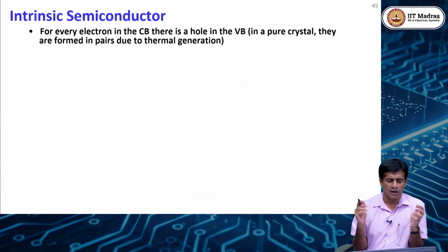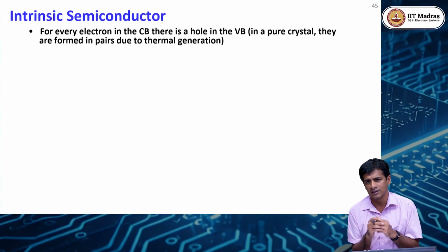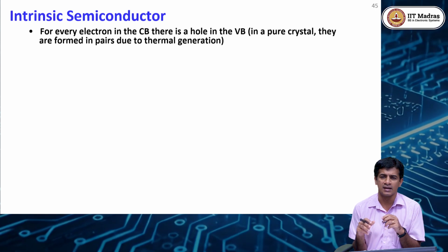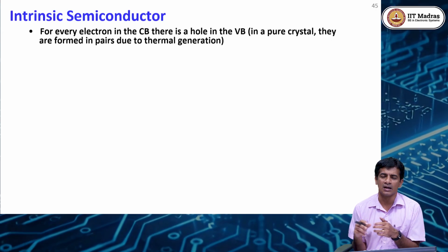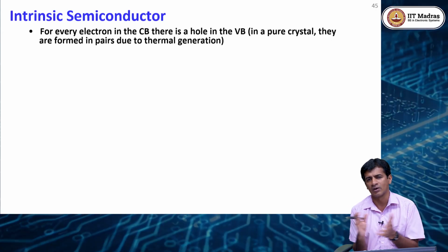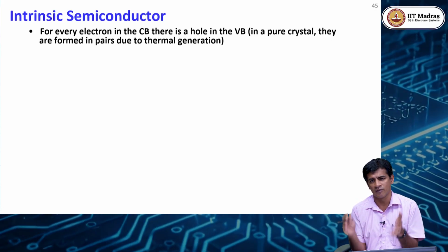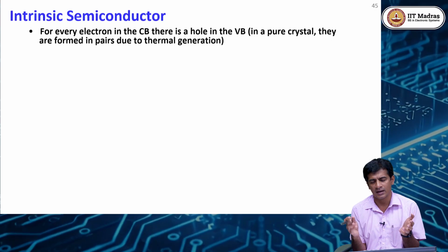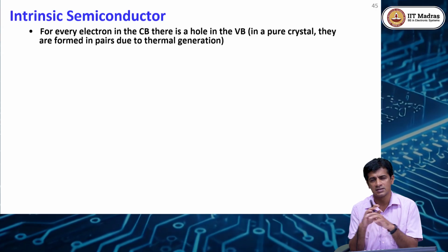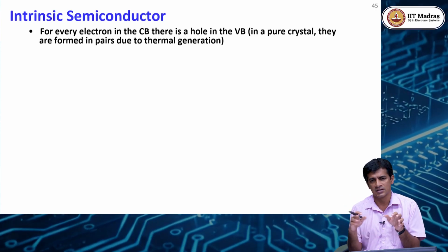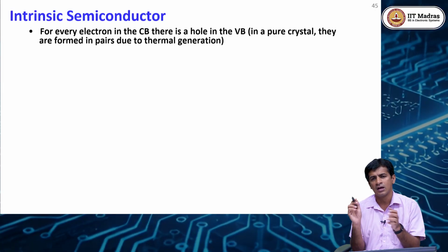All right. So now let us see. Having learned how to calculate the electron and hole concentration, let us take the case of an intrinsic semiconductor. An intrinsic semiconductor could be considered the purest form of material. You do a lot of chemical processing to create an intrinsic semiconductor. For example, silicon consists of only silicon atoms. Let's assume there are no defects, or that the number of defects is far lower than your detection limit.